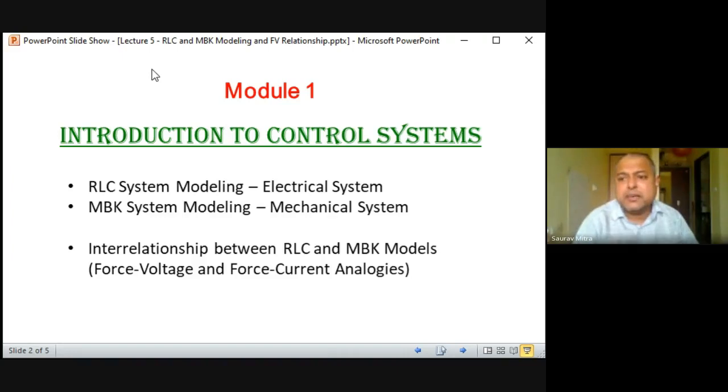That we will see in the consequent lectures, because I told you control system is all about three things: gain, stability and energy. The more the energy, the more the gain of the system, and the more the gain or energy, the more unstable the system becomes. So for every system we try to analyze stability, pole position and all those things. All the stability and pole positions can be found only if we know the pole position. Pole position can be found from the system transfer function, and the transfer function gives the characteristic equation. From there we find the pole position. So this is the relationship of all parameters.